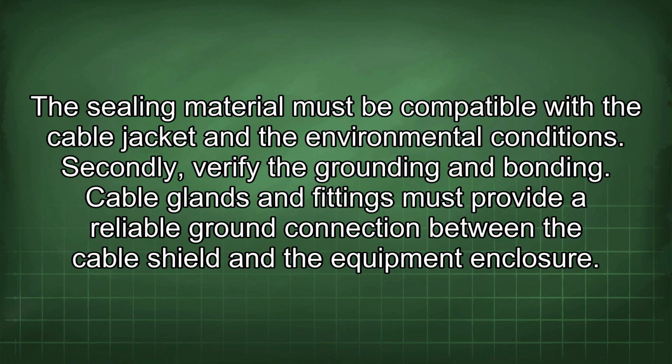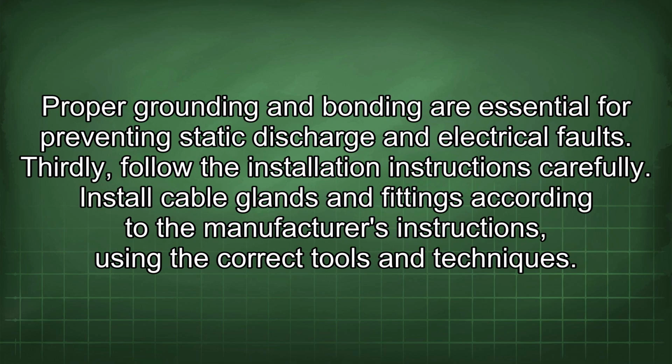Secondly, verify the grounding and bonding. Cable glands and fittings must provide a reliable ground connection between the cable shield and the equipment enclosure. Proper grounding and bonding are essential for preventing static discharge and electrical faults.